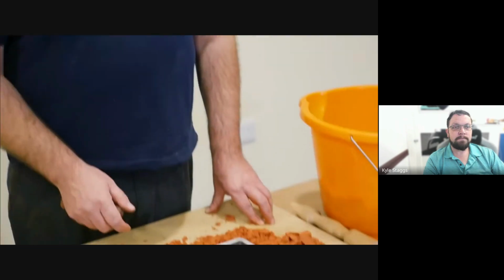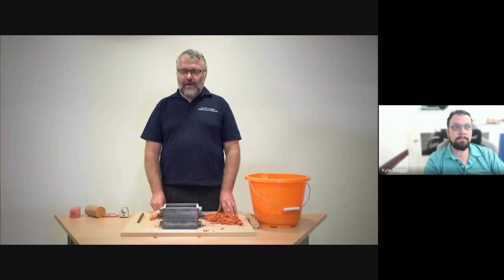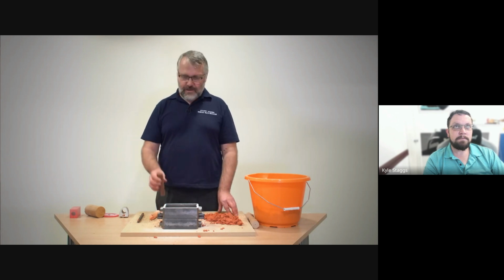We need to find a way to introduce the metal into the cavity of the mould. We do that by adding a runner. If we were doing a pattern which needed it, or if you were doing an educational course, you would always need to talk about having a riser, which is a second channel on the opposite side. For this particular task, we only need to have a runner.